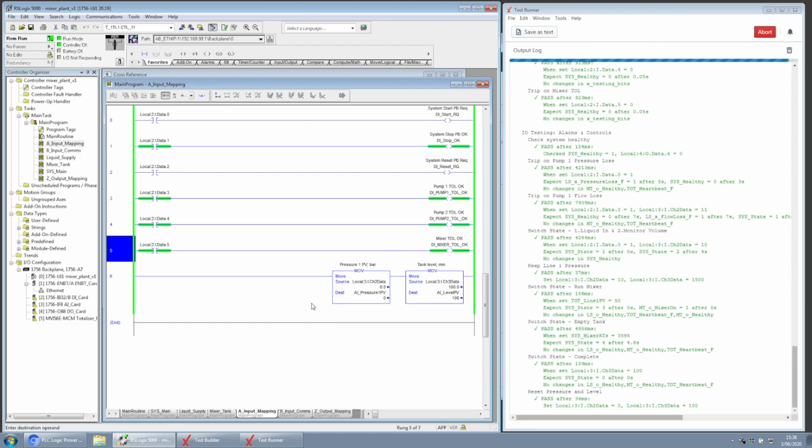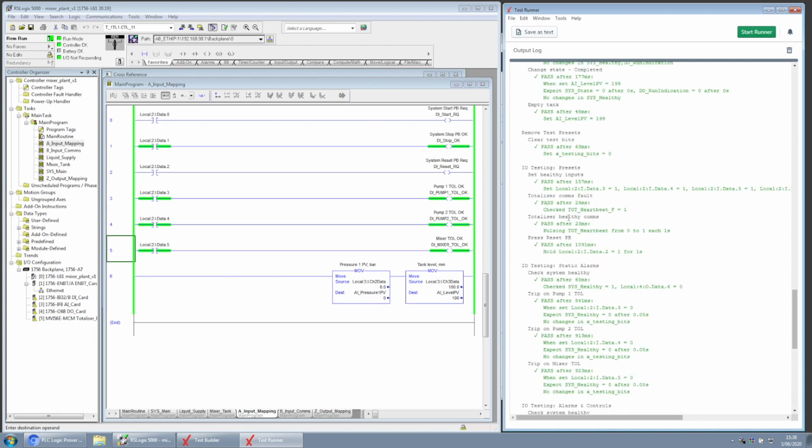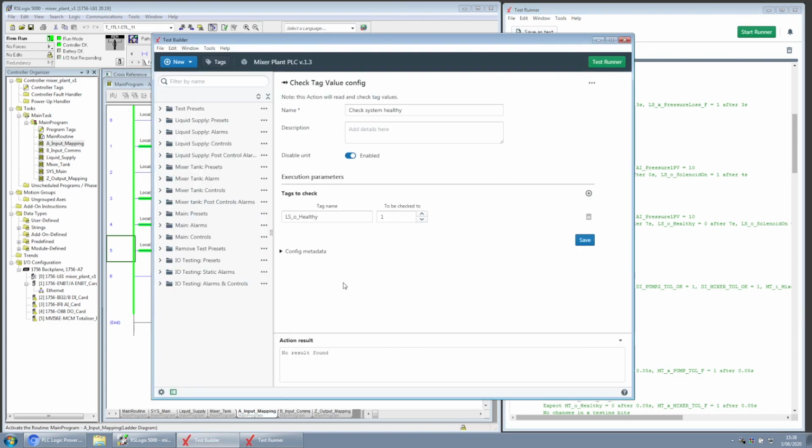the functional description. As we can see, it went very quickly, went through lots of tests in just 1 minute. It completed completely automatically. It went through all these tests without any human interaction. So we can create and build the test cases and run them before modifications and after modifications, to make sure the integrity of the PLC code is the same.